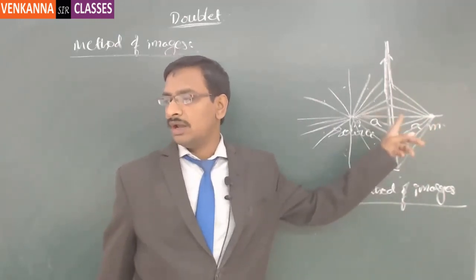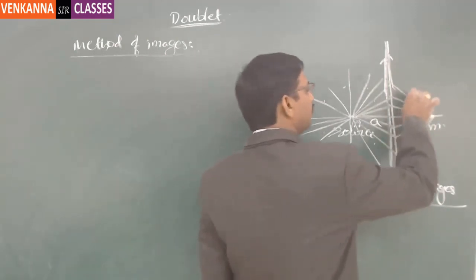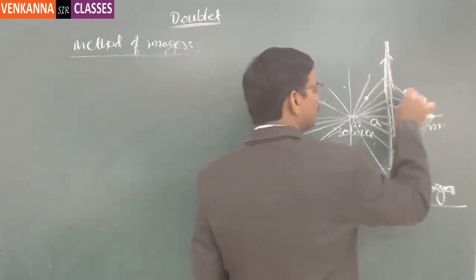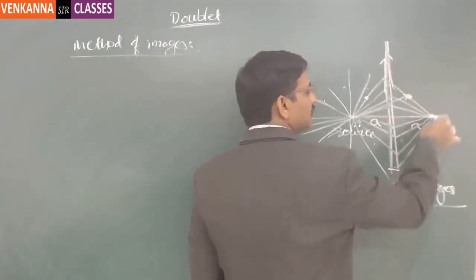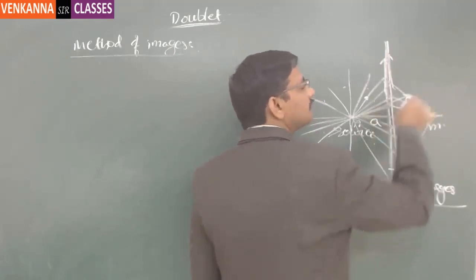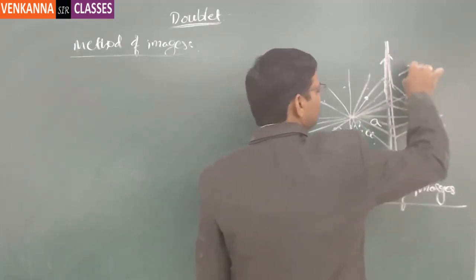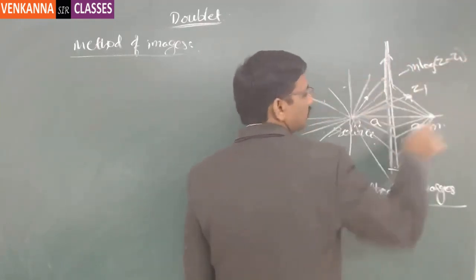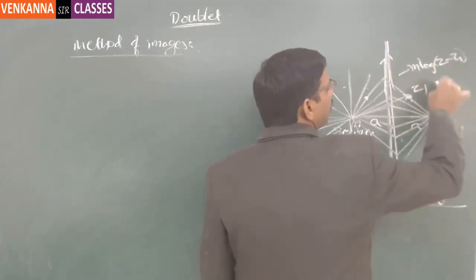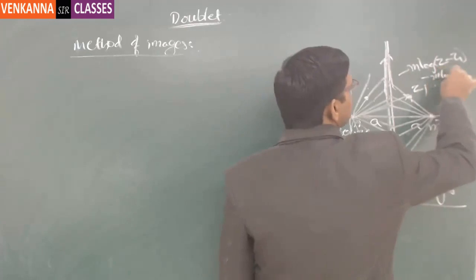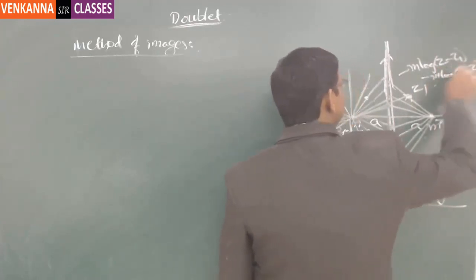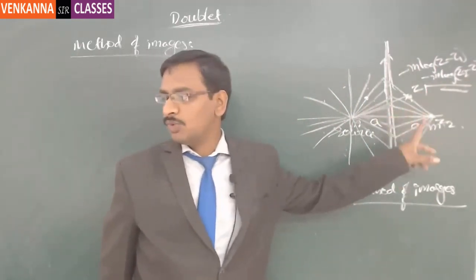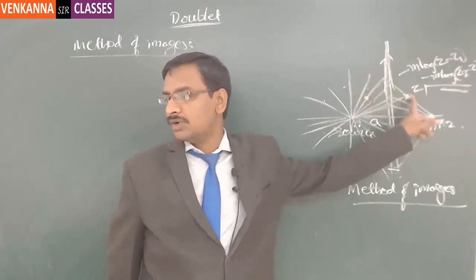So these two together will give the complex potential at any location, maybe here, or maybe here. It will give the accurate value. So if you wanted to find the complex potential here, then from this location how far it is, and from this location how far it is. Let us say the coordinate of this is z1, then this is minus m log (z minus z1). If you treat this as the coordinate axis, and this is z2, then minus m log (z minus z2). So this is the complex potential at this location. That will be the perfect complex potential, because the presence of both together will assure the flow at any instant you can think of. Got it?